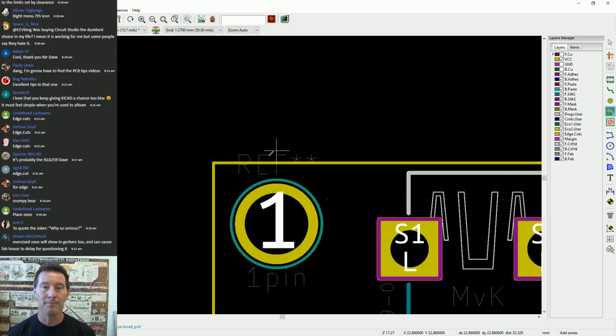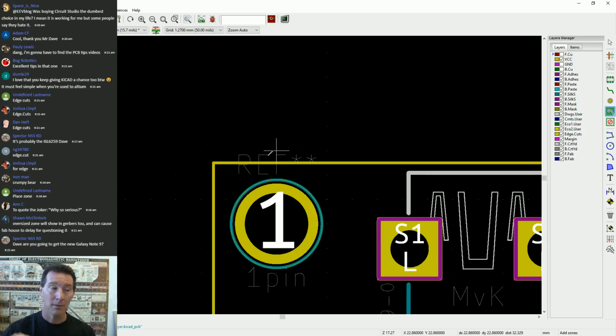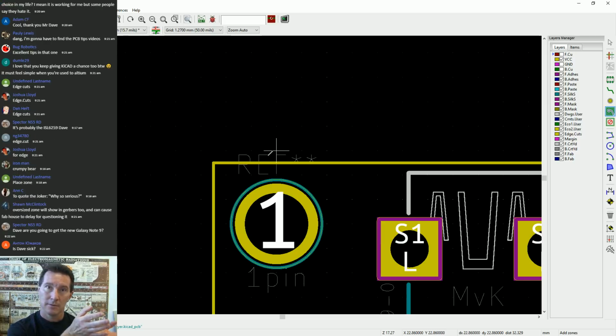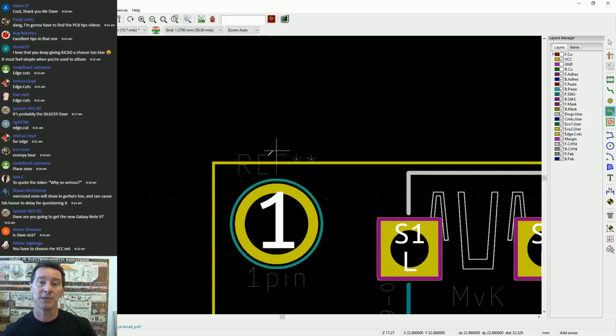And when they chop your board up, especially if it's a multi-layer board like we're designing here, a 4-layer board, that means we've got the top copper, the bottom copper, and ground and VCC in here. What we're doing at the moment is creating these two inner layers, ground and VCC, and they're just one big solid copper plane in this case. Doesn't have to be. KiCAD does not have planes as such. They're just layers with polygon fills or zones.